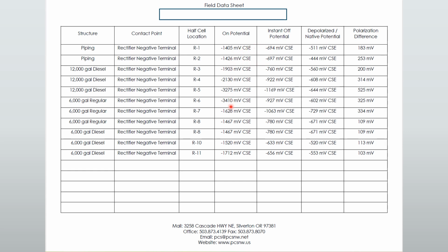all these values, yeah. Your on value is going to be higher next to your anodes. So you can have strong anode values. That's probably why we had strong polarization. The lower the anode, the lower the on value. We talked about the IR drop and being able to calibrate it. After a while, you can kind of get a feel. You put your reference cell on the ground, you can see your on value. If you're already several measurements into a site, you can kind of anticipate what your instant off value is probably going to be after that as well.